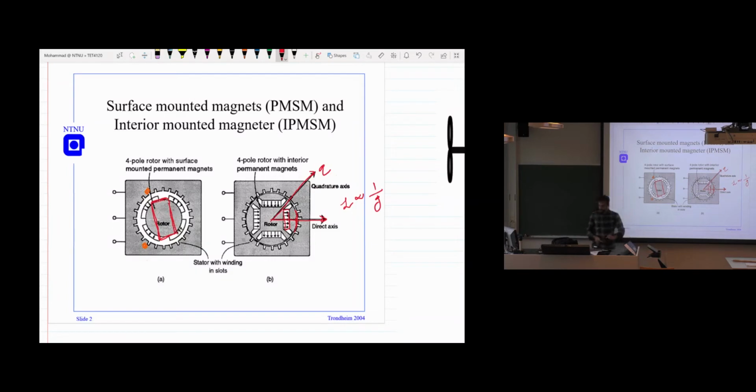In this one, we are defining the axis, something like this is the d-axis. And here we have the q-axis. So in the original machine that we are discussing, here we have the q-axis. And this is the magnet or the rotor inside, like this, not symmetrical, it's asymmetrical. In the q-axis, we have the larger air gap compared to the d-axis. So you have the q-axis, larger air gap. This means you have a smaller inductance in the q-axis. And that's the regular machine that we are discussing.